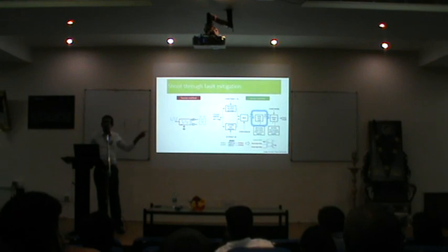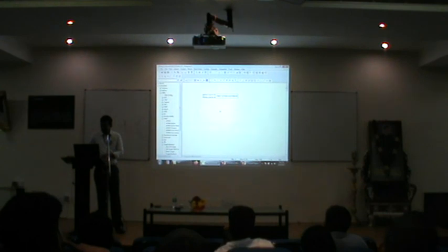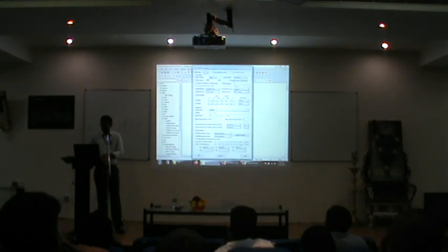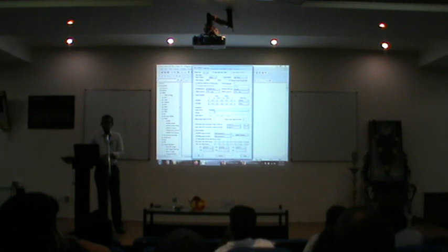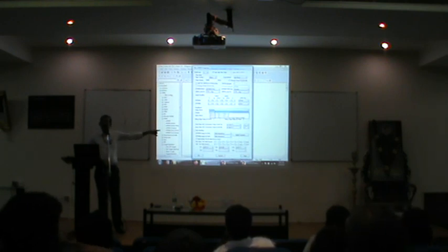That also is there in these C2000 controllers. And once again, coming back to our AICTE Embed, you see how easy it is to control our deadband. See this particular thing, deadband. You have the configuration. As of now, it is disabled. If you want, enable it. While you enable it, also there are plenty of options available. All available at just a click, a mouse click.